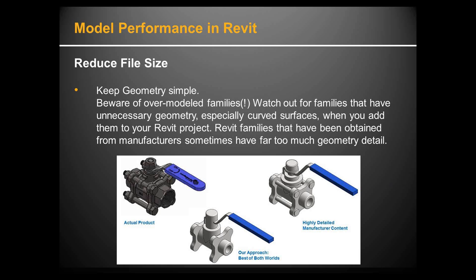Yeah. No, this is always a problem. Pulling families in, or using manufactured families, boy, they tend to go overboard, and they tend to create something in SolidWorks, and then it's got a gazillion facets on it. So these are things where, do you need that detail? If you do, then find a way to use it and keep it minimal in your model. If you don't need it, just create a box that's the right size as a placeholder and use that for most of the time. This is one of the biggest sucking up of memory things there is out there.